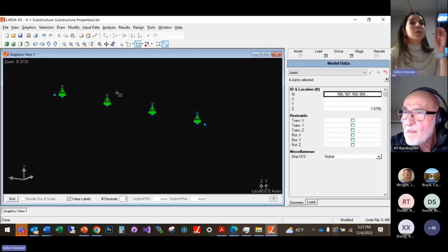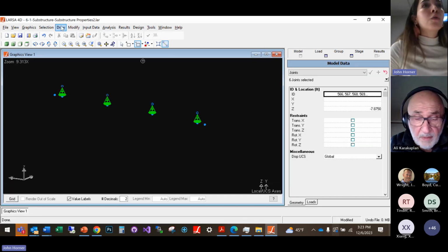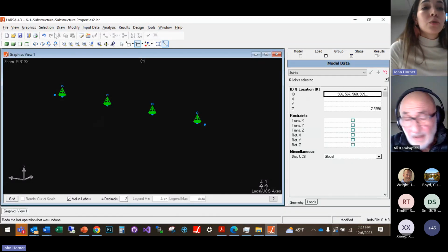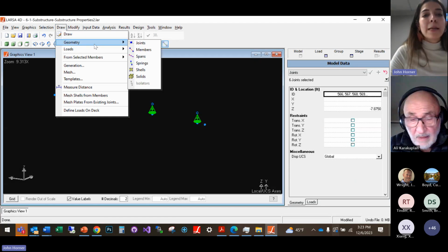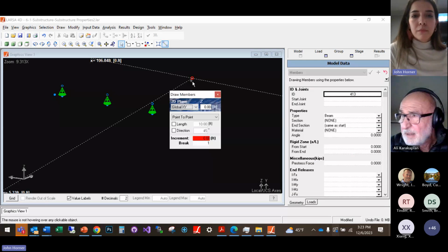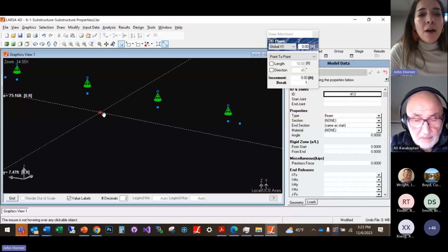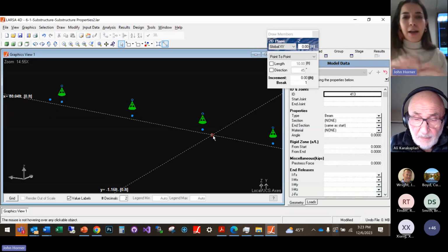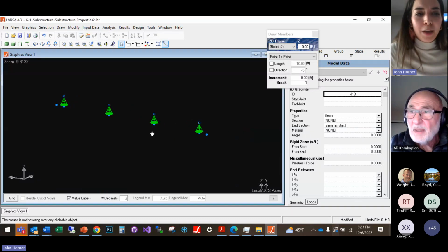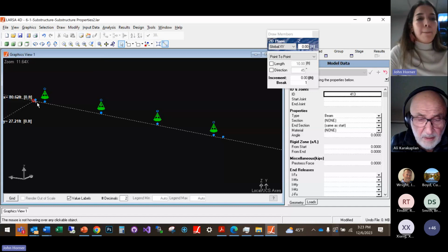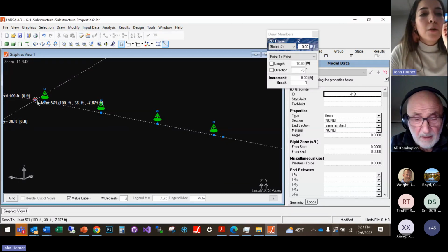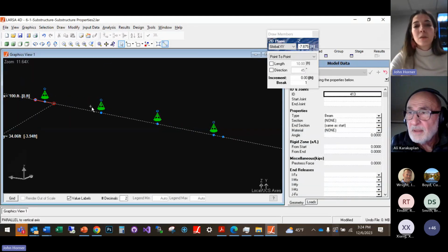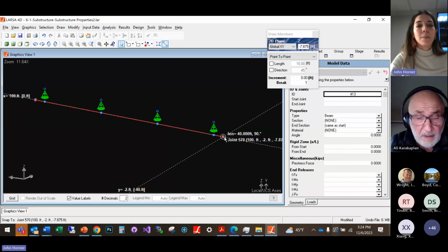After unselecting the joints with the restraint, you can take draw tool again. In the main menu, while the graphics view is active, go to draw, geometry, members, and now we will draw a single member, not multiple members, because I want to show you a tool for meshing. We will draw one member between the first joint, the leftmost joint to rightmost joint. Okay, single member.